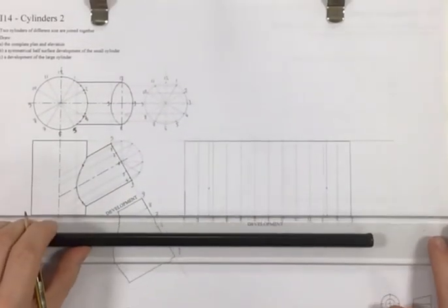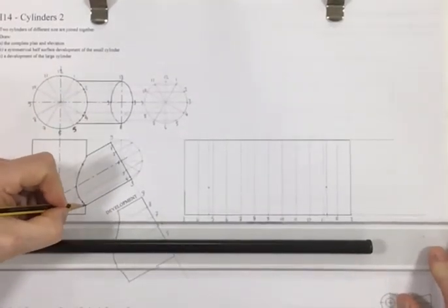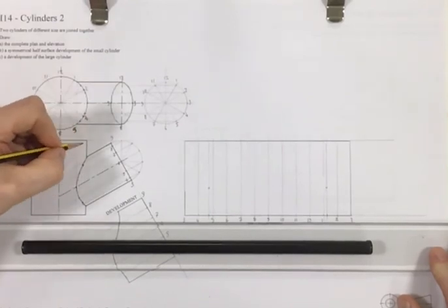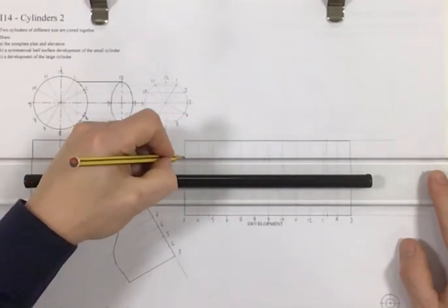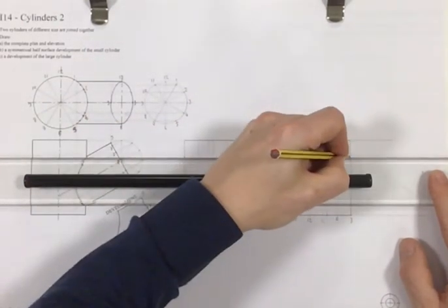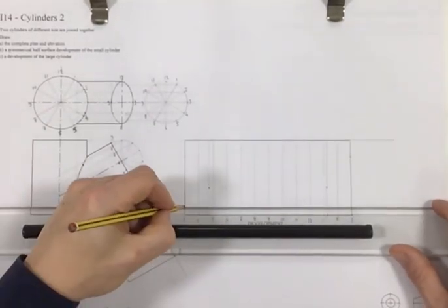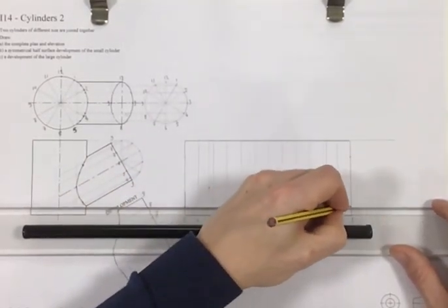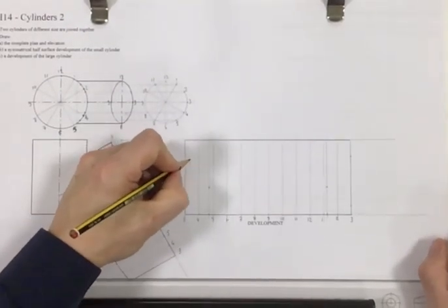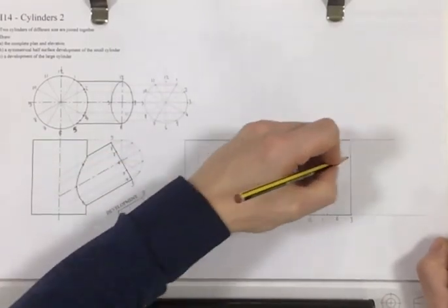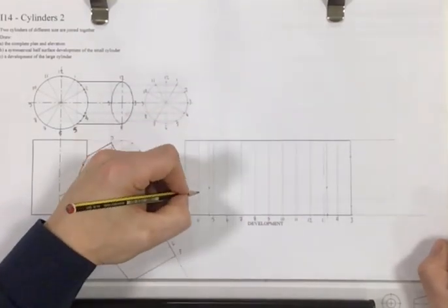We also know that the top and the bottom of number 3 feature here. So we can start here with number 3, project it across to the same number 3 on the other side, and the bottom of it is there. So we're going to have a half curve that comes around here, and another half curve that comes around here. We just need to find the height points now on this line in between.